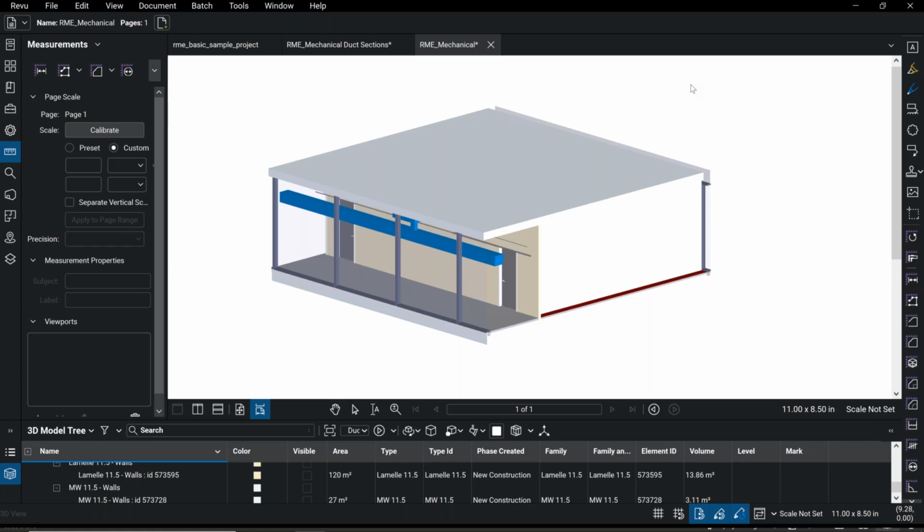I'm not familiar with Chief Architect, but if you go to your export or to your output, if you can export your file as an IFC file or as a U3D file, the IFC is kind of the standard format that's being used. And as long as you can export to the IFC, Bluebeam will create the 3D PDF from the IFC file.